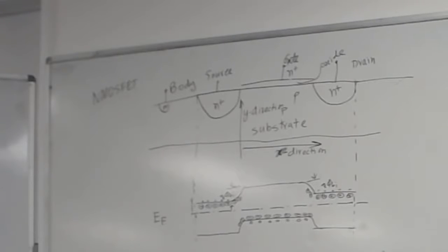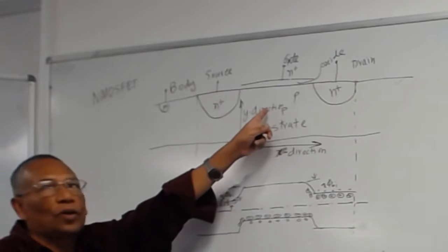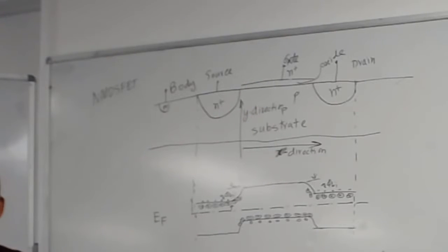That you have one guy who goes into the box, and then some guy has a saw, and cuts the box in half, and then puts it down, and then hands are moving, legs are moving. Use the same technique to draw your diagram going from the gate to the substrate. So you first draw your PN junction, then put it in a box, cut it with the saw, remove the box, then you'll get your energy diagram from gate through body to the substrate.